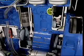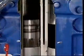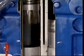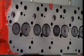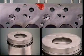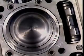A connecting rod links the crankshaft to the piston. Pistons in 2- and 4-stroke diesel engines can change directions hundreds of times a second and are exposed to extremes of heat and pressure. Modern pistons are made of aluminium alloys. Diesels using direct injection have an almost flat surface on the cylinder head, and almost all of the combustion chamber is in the head of the piston.